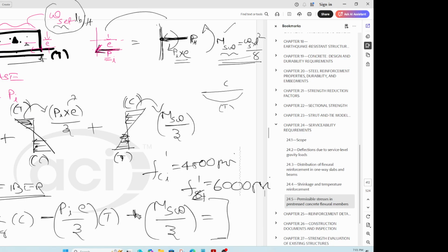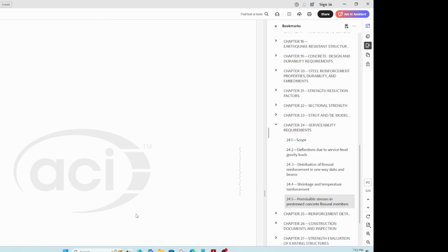Now let's talk about the final stage, which will be split into two categories again. For example, let's say you have your beam ready now. You have already cut the ribbon, right? The stress is already in, and this is ready to be installed. So you pull it here and then support it on, let's say, two supports, right? Now the compressive strength of concrete, f'c, has reached its final value. Let's say that is 6000 psi in this case, right?